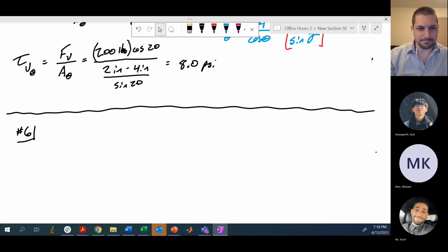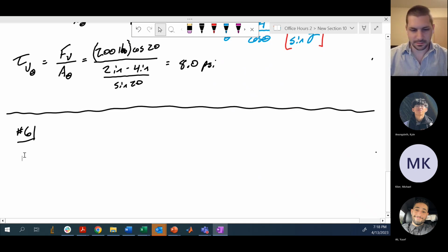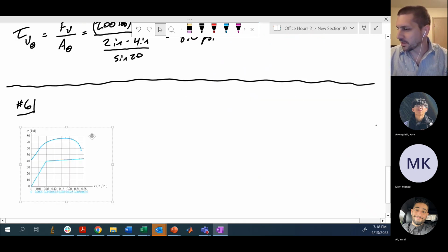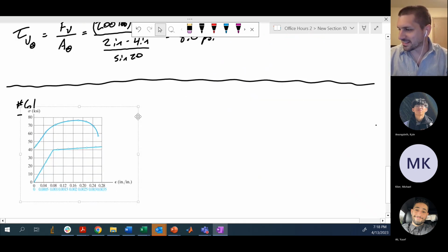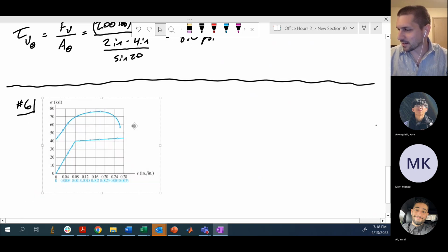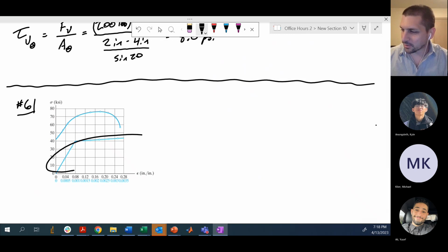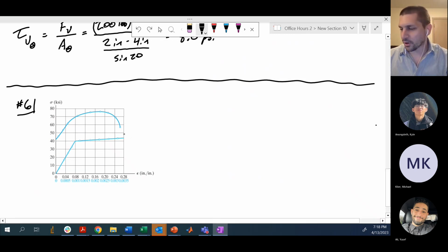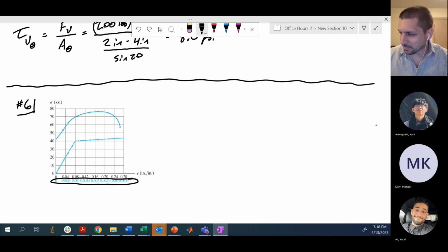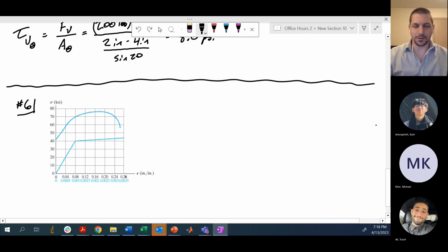And we've got this interesting looking stress strain curve. You've not seen something exactly like this before, but it's got this two scale again, right? Where this lower curve would use the lower scale because it's trying to blow up that very stout, short linear region on the front end of the test.